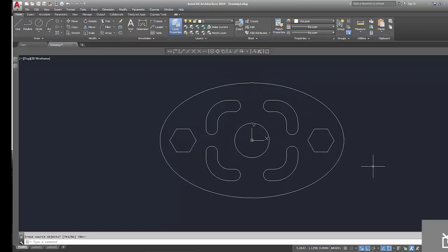So in this exercise, it's good to kind of break it down if you can in pieces. And what we did first was we drew the circle. That was low-hanging fruit. Then we did the ellipse. We drew the polygon, the six-sided polygon. We know that it was circumscribed about the circle with a radius of 0.5. We drew it at the center of the object at 0,0, or the center of the circle. Once we drew it there, we moved it over 3, and then we mirrored it about the center of that circle.